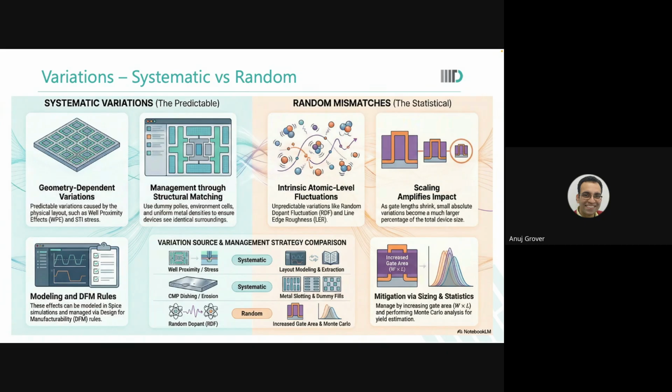And it is not just about stress. Even word lines see similar density, bit lines see similar density. For every metal layer or every layer that you are designing, keeping an environment cell ensures that the proximity is the same. This is very, very important for memory cells also because we do a lot of DRC violations.